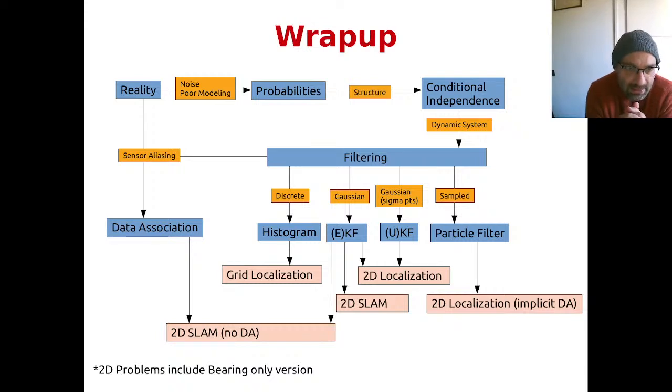And this made us decouple the problem of constructing an estimate which is affected by sensor aliasing into a problem of determining which measurement belongs to which state variable, which means measurement to landmark in this case. Once this is known, we computed the next estimate by running filtering. To this extent, we introduced the problem of data association first in its general form, and then we boiled it down to 3 simple heuristics, which are the most commonly used in the case of the filters.